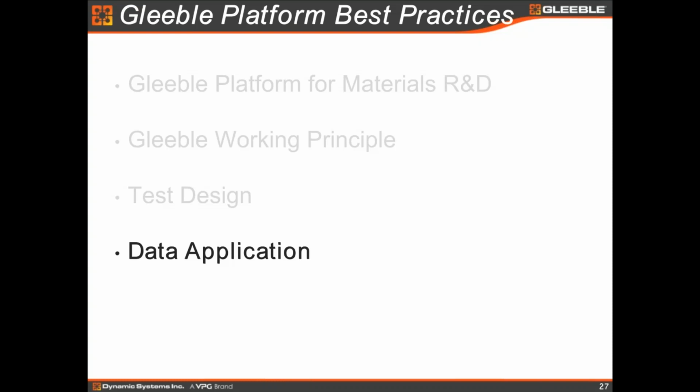Of course, there are some other tests which can do the same thing too, but for a forging piece process simulation, if you want to know the distribution of the microstructure or property, or if there is a potential for cracks at any places, Gleeble test alone is not enough. You need to combine it with the FEM model to give you a 3D picture of the workpiece during processing.